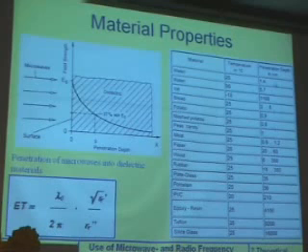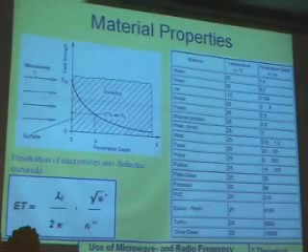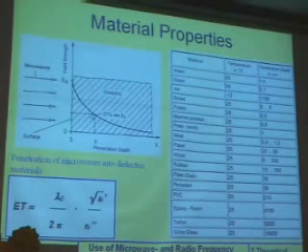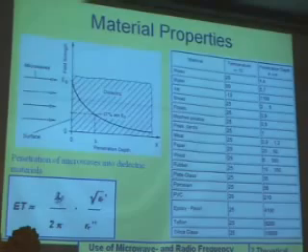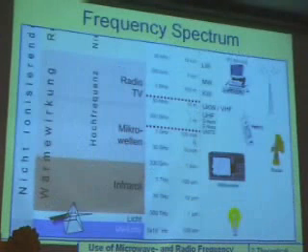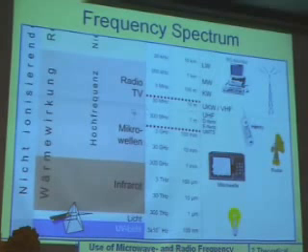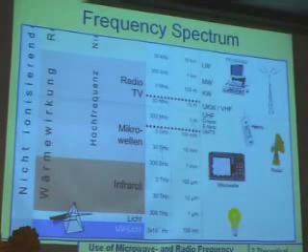And this is a clear sign that if you do not slice the material into certain geometries, you will not have any chance to get microwave energy into the product. Or you have to change the kind of energy and go to a kind of energy with a higher wavelength. Here you see the wavelengths of several meters compared to microwaves with several centimeters. Therefore, theoretically with high frequency, this is the frequency with lower frequency than microwaves, but higher wavelengths than microwaves, you have higher penetration depths.